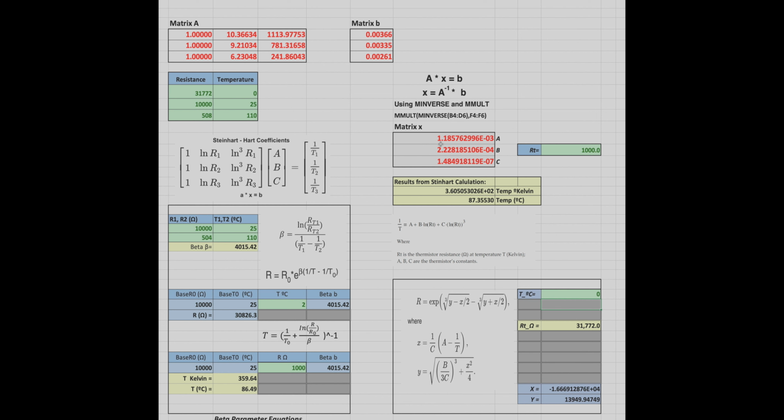The Honda sensor is within about half a degree. It maybe reads a little higher because there may be a little bit of self-heating enclosed in the case. It may not be able to dissipate some of that self-heating, which is probably not much because we're just dealing with milliwatts as far as the dissipation. But it's still very close.